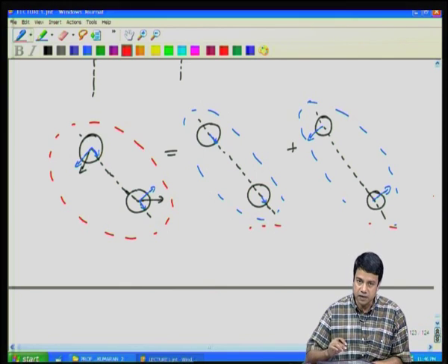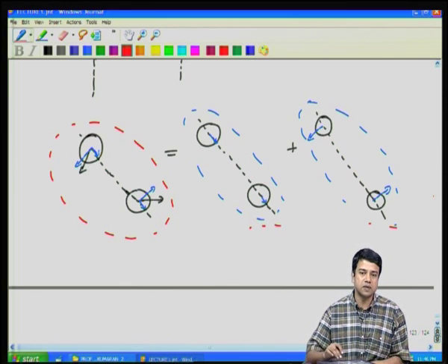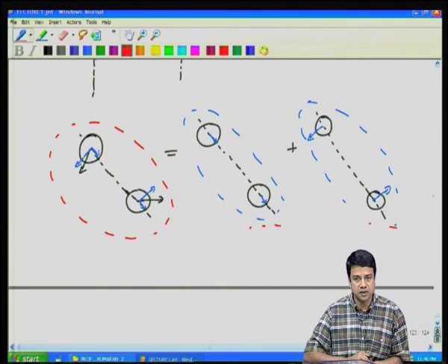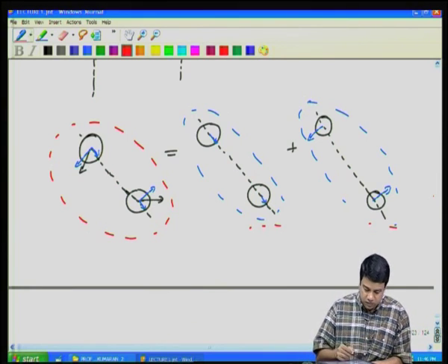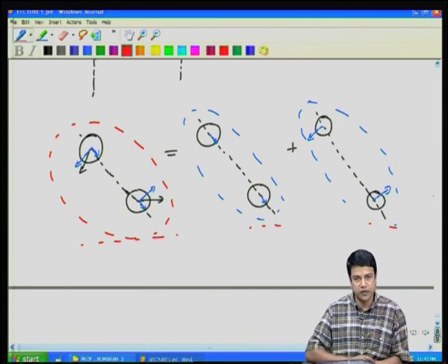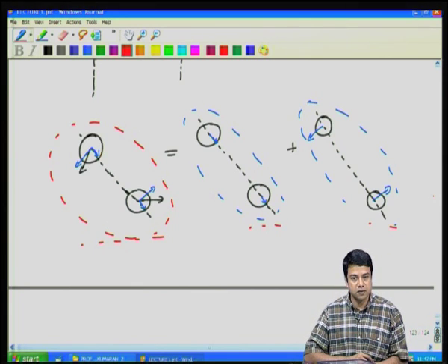If they are satisfied individually by the velocity fields in these two cases, the sum of those two velocity fields also satisfies those equations. The sum of the velocity fields satisfies the boundary conditions. Therefore, the sum of the velocity fields is a solution of this original problem. So, that is the advantage, you can use linear superposition in order to solve the problem.